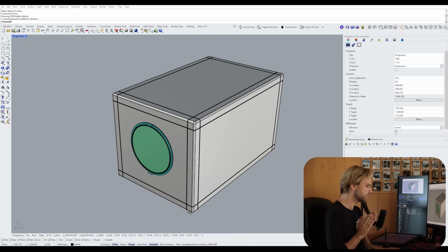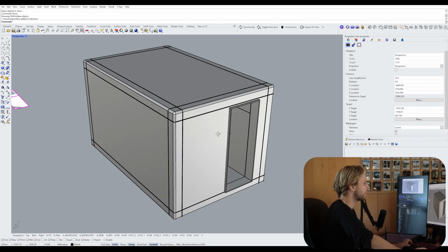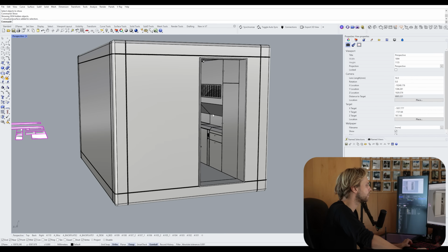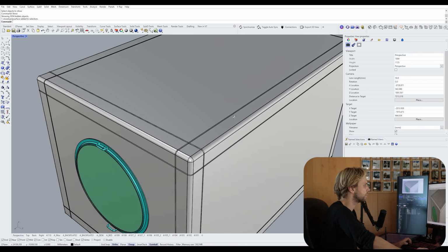Okay, so custom Rhino unwrapping and then texturing, right? When do you use it and for what reason would you use it? In most cases, at least in architectural design, you don't really need a UV unwrap. But when you have geometry that's pretty complex, or when you want textures to map perfectly on top of geometry, then you use custom UV unwrap.